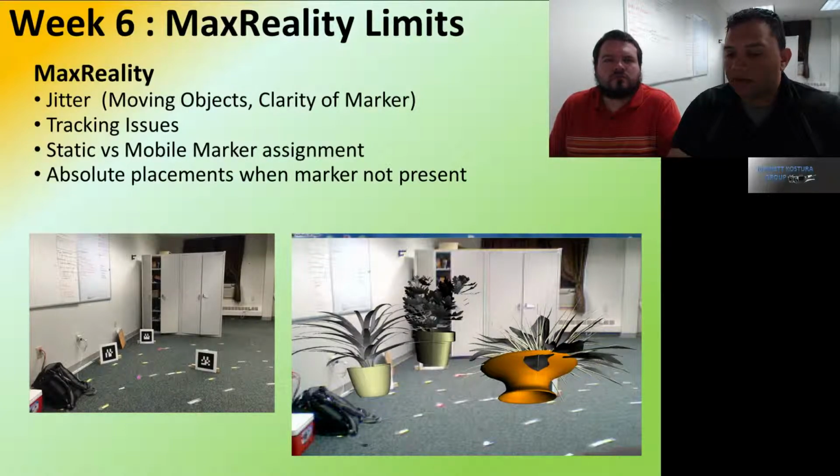So as opposed to before, I believe the jitter has to do with the system trying to figure out, okay, that's a marker, and at what angle is the marker currently fixed, and let's represent the object. And since it fades in and out with the resolution of the camera, it might get a slightly thinner edge, which then obviously calculates to a different angle, which is, I think, where that jitter comes out.